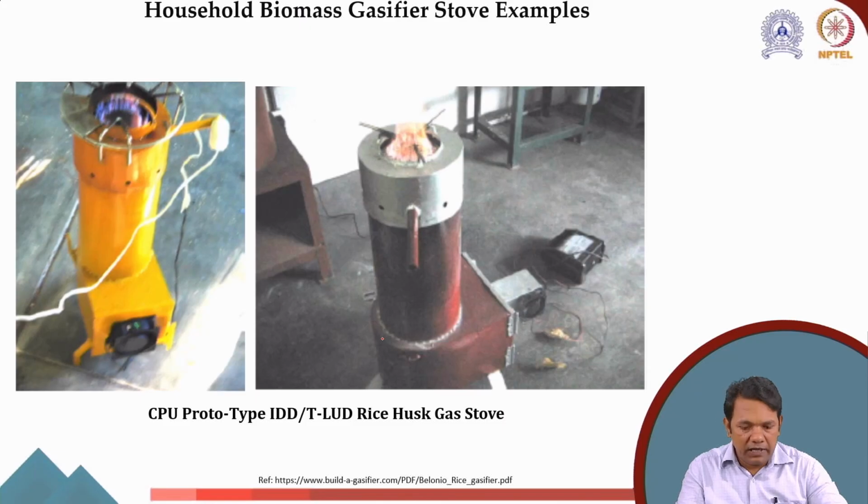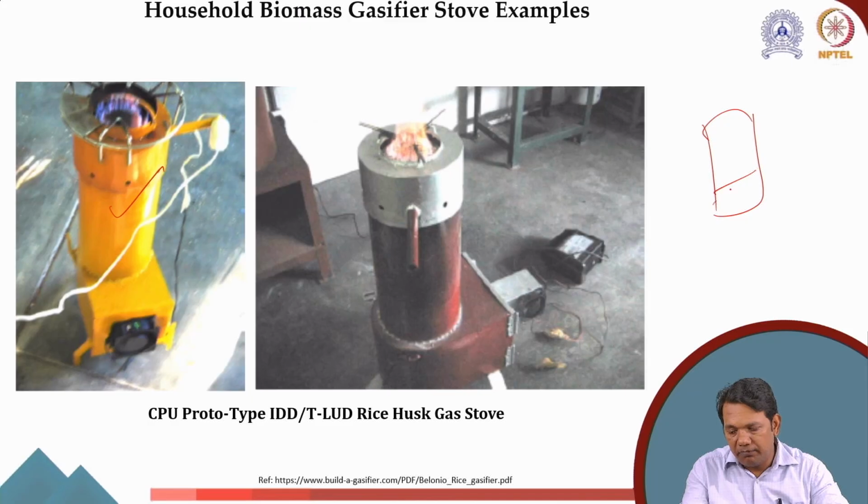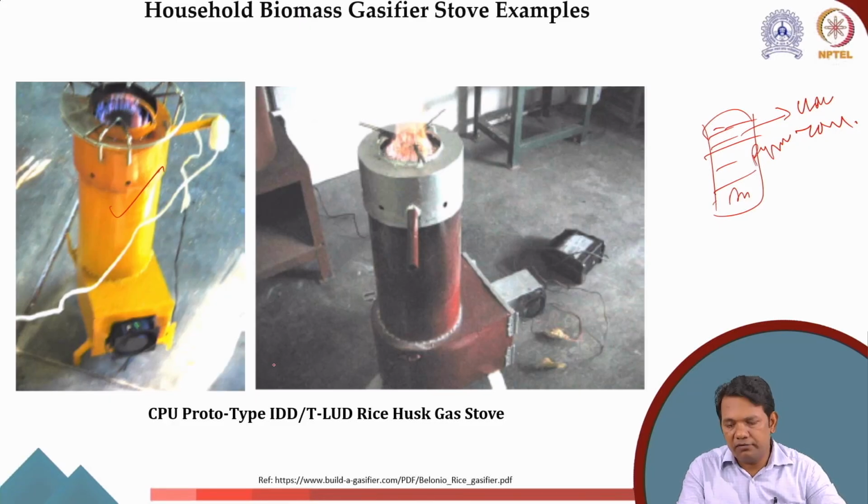Now another kind of household biomass gasifier stove is this CPU prototype. You can see here this is an inverted downdraft gasifier. So you remember inverted downdraft, that means my biomass is here, this is my pyrolysis zone, let's say, and this is my char zone. Okay, these two images actually show the inverted downdraft gasifier. The air goes from here.